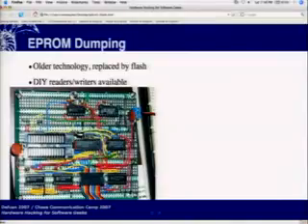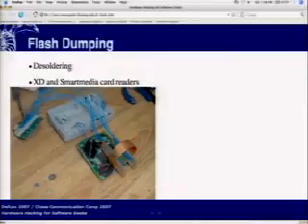Another thing where resources from the embedded engineering or forward engineering process come in handy is when you've got decompiled binary. So the first thing you look for are vectors that are defined in the chip spec, like the reset vectors, the interrupt table vectors, and figure out where the code starts and where it goes when it jumps from the code it's executing to an interrupt, and then back. The general first interrupt that's going to get serviced when the chip starts up is the reset interrupt vector. If you can find out where that is, that's the entry point for your code. You just tell IDA this is the entry point and it'll figure it out. Exactly, the G spot as it were.